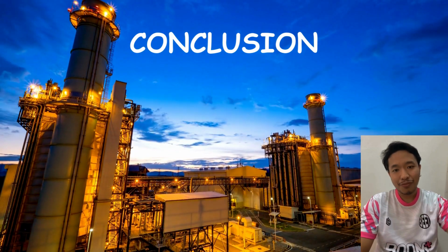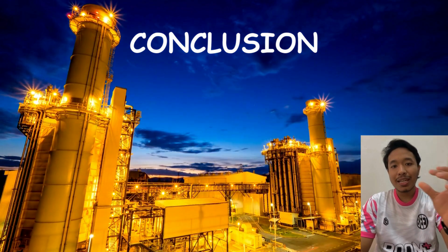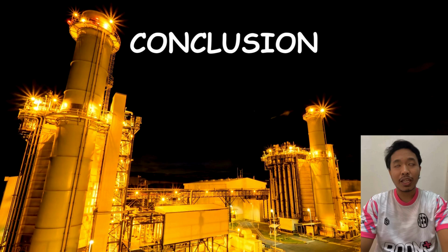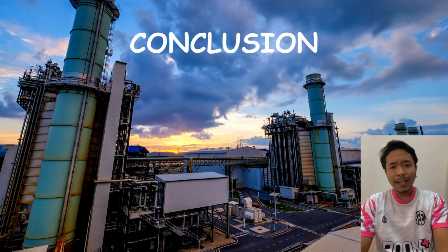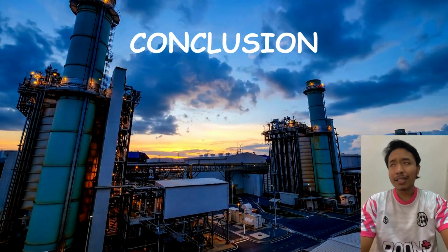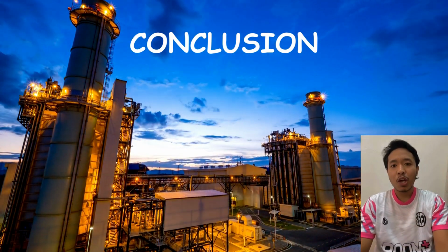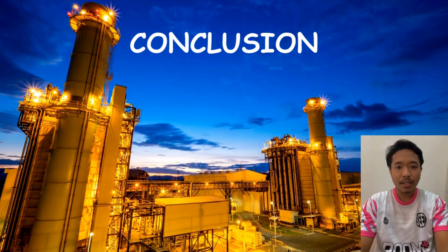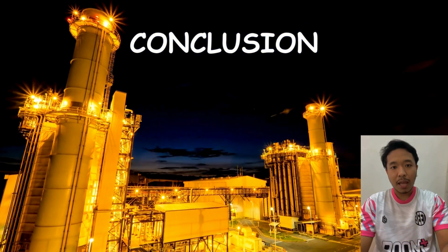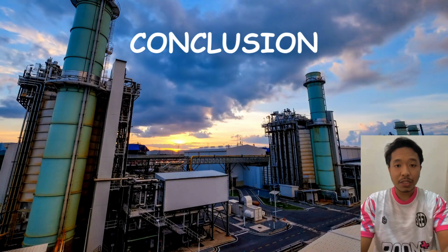The second is the surface condenser, which keeps them separate using tubes. Direct contact types are simpler but need high purity water, while surface condensers are more efficient and prevent contamination.